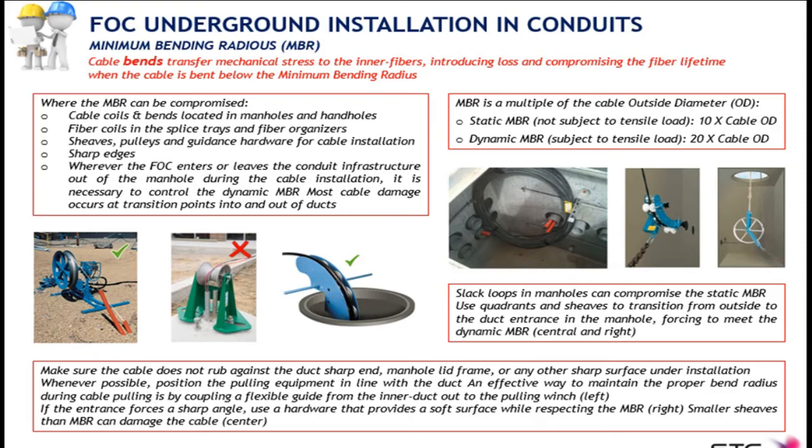On the fiber types changing the minimum bending radius, please do not mistakenly confuse the minimum bending radius of the core fiber inside the cable and the minimum bending radius of the cable itself. Different types of fibers, such as the G657A, B, and so on, are bending insensitive, so they have better bending radius performance compared to the standard G652D fibers.